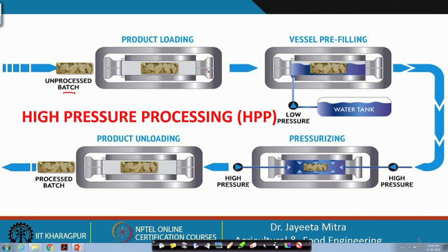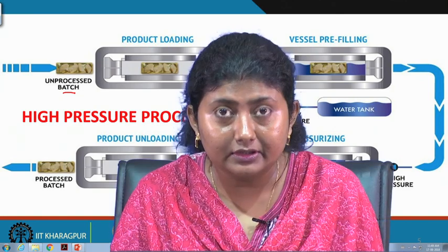After that the vessel pre-filling is done. So, the water is entered from the low pressure channel to the chamber where the pressure is intensified to a very high extent, and the food is exposed to that high pressure. So, after this pre-filling the high pressure generation starts.